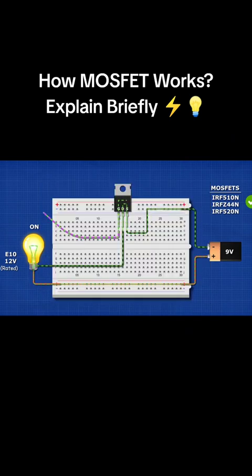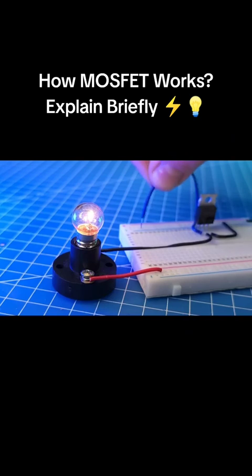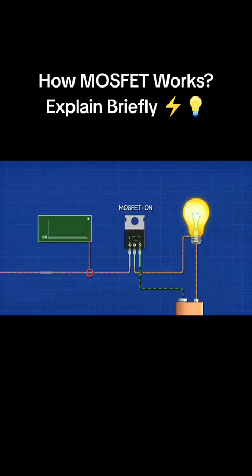We can discharge the terminal by providing an exit to ground, which will deactivate the MOSFET. When the MOSFET is fully on, no current flows on the gate terminal. But when the MOSFET is changing from off to on, electrons rush into this terminal for a split second, and so there is a large inrush current flowing here.